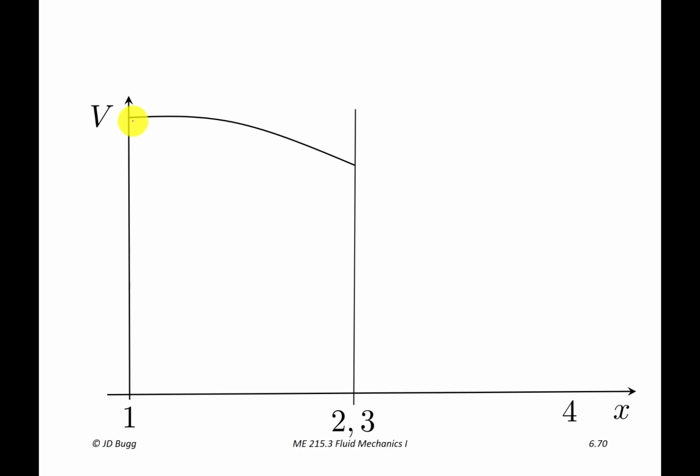And as the air approaches the rotor plane, it's slowing down. So it's dropping, dropping, dropping. And in this illustration, I've got it dropping down to here. So v2 is this value. So our axial induction factor here is the change in velocity, so from there down to here, divided by this velocity. So it's relatively small, maybe 10% or so, 0.1 for an axial induction factor. But the key thing is the velocity is decreasing. So that's fine. So the velocity decreases as it approaches the rotor plane.